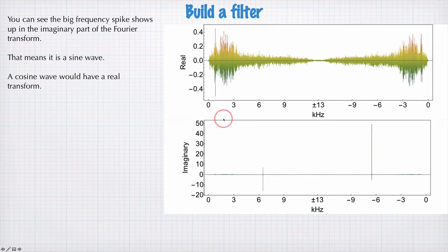The plot of the frequencies here you can see is done in the default way for the computer to think about the Fourier transform. So it goes from 0 to plus the Nyquist frequency, then down to negative Nyquist frequency, and back up to 0. The first data point here is the 0 term, so that's where it tells you how much amplitude you have at 0 frequency. The last point here is a slight negative frequency just below 0. And the reason why I mention this becomes important in a bit.